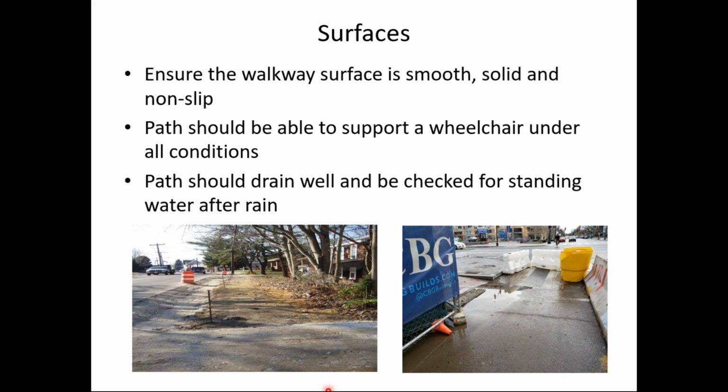The photo on the right here I took in Washington, D.C., actually just before COVID. I was in town for a conference. Notice they have a nice wide, that looks like almost 10 feet wide, pedestrian path here, and they have the temporary traffic barrier separators here, because this is, you can't see it, but it's a multi-lane street. I don't really like the way, because there's really no good guidance or edging to me to get pedestrians to the sidewalk.